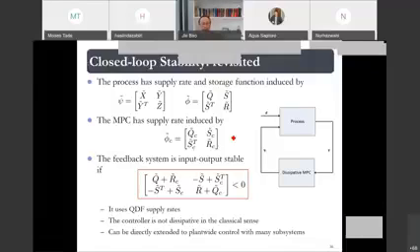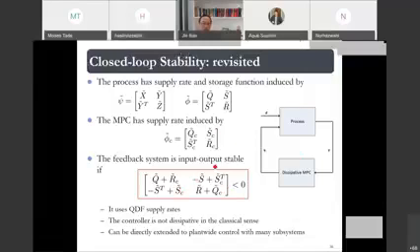Okay, so basically we can derive the same idea. I can skip this slide. Basically, it says that using this concept, we can have very similar results as the dissipativity stability design we had before for the model-based control. So if we have the supply rate of the controller given by this matrix, then this is the condition that ensures the closed-loop stability.